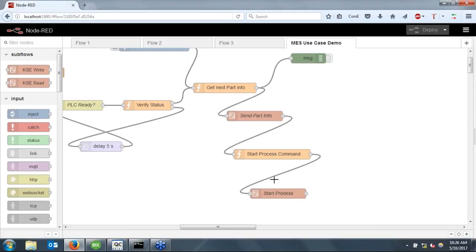This is where we're going to be pulling in that data from the PLC with explicit device reads to the KepServerEX HTTP server endpoint. And then we're able to log these to a disk while we reset the statuses and set up the line for the next component to be worked on by the operator.